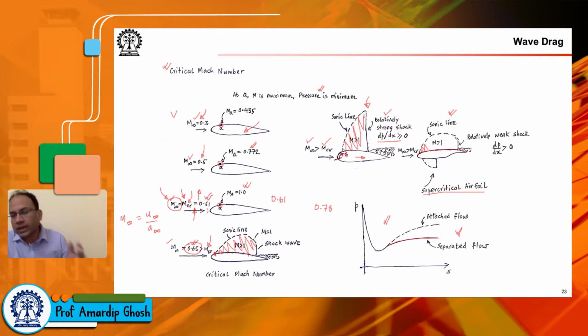If you think of flow with area change, you will see that the flow acceleration is somehow related to the thickness of your airfoil. Thicker airfoil, more acceleration and deceleration. Thinner airfoil, less acceleration and deceleration. So in this particular design, you have a more distributed supersonic flow region that, as you can see, doesn't extend far away from the wing.